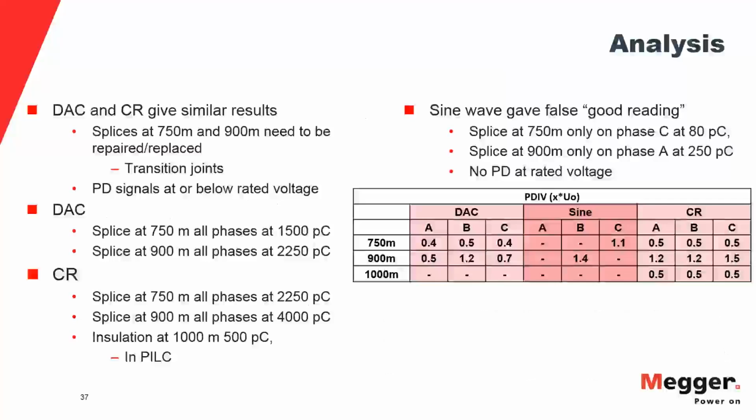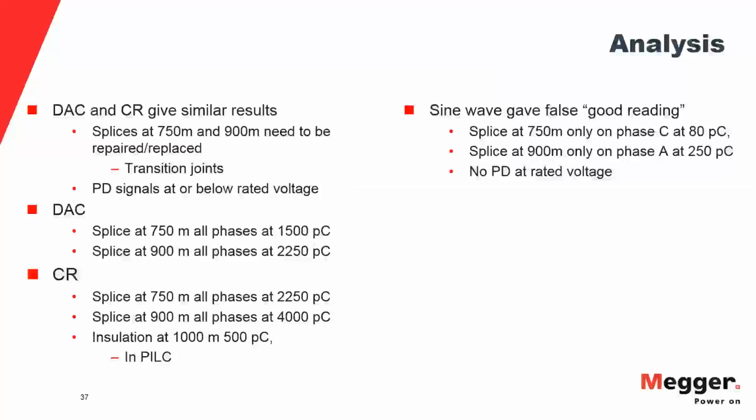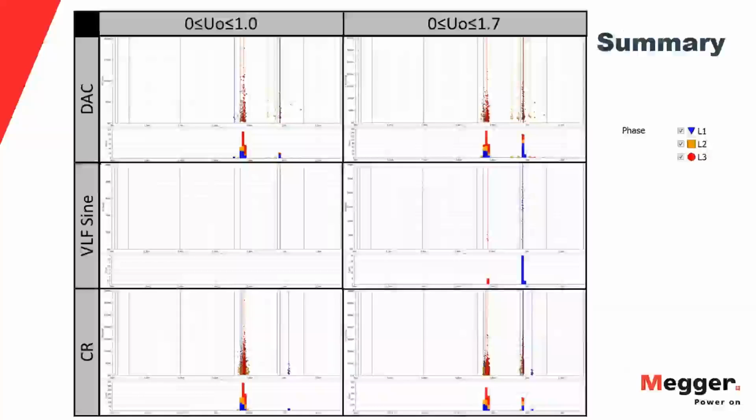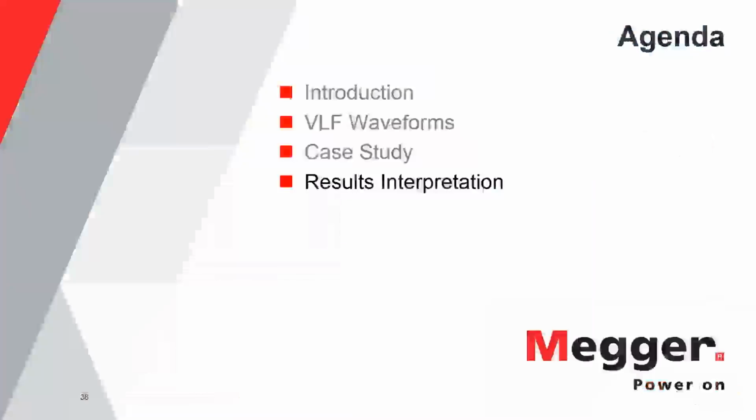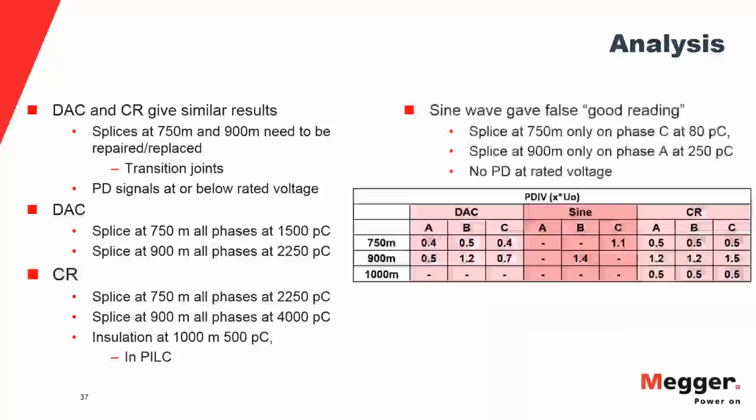And the square wave and specifically the triangular wave are not really common. There's no equipment really commercially available, and it's not supported by standards. So it's sine or cosine rectangular, and then keep in mind in what world you're operating, IEEE and IEC, and there are different test values in those two worlds, and just apply the voltages accordingly.